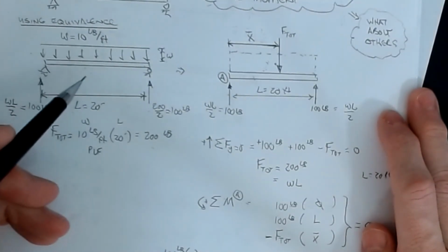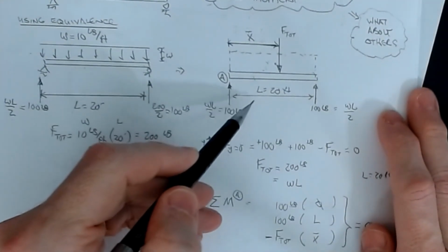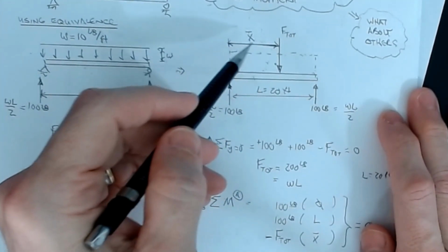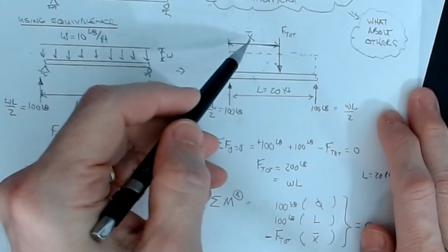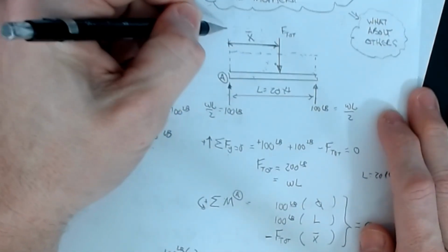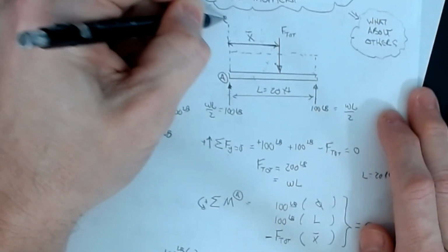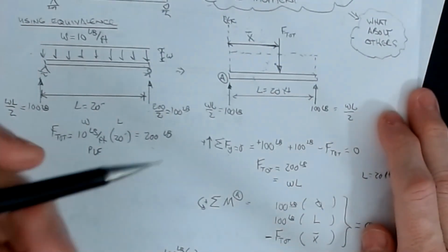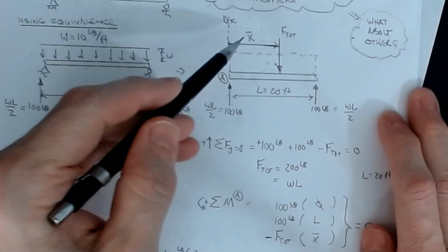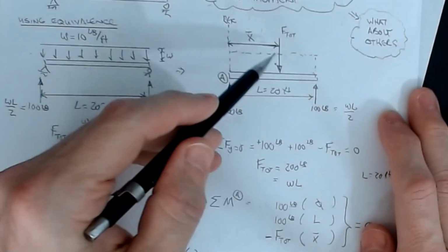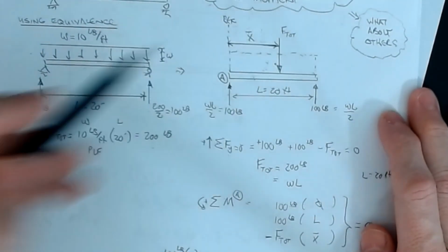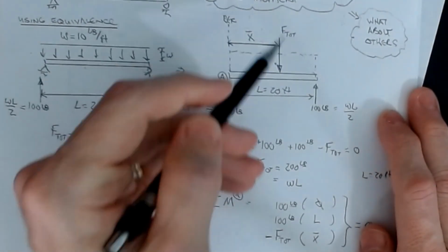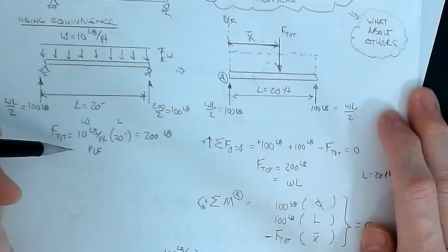Now, for this system to be equivalent to this, I want to apply a single force somewhere on the beam, at a position of x bar. What we've done is, again, set the reference relative to the left side. You can choose it anywhere as long as you're consistent. That's fine. But my x bar here is an unknown. We don't know where this force is applied, but I do know its value now, because I got it over here. When we were doing equivalence of areas, this resultant force was the total force happening on this thing.